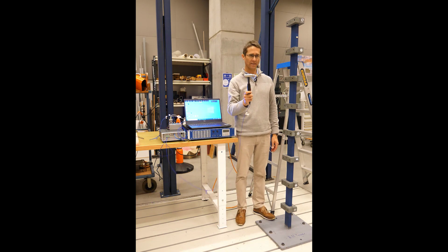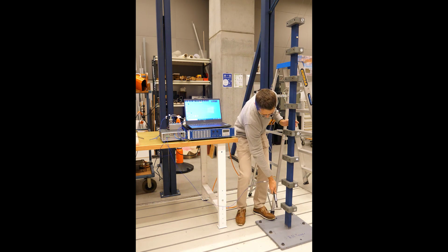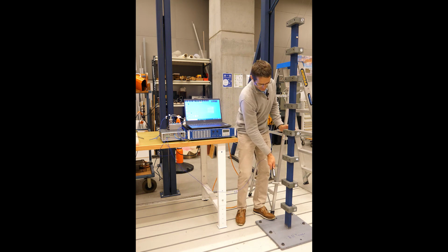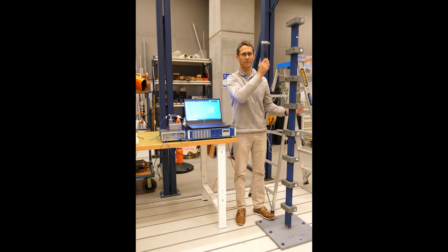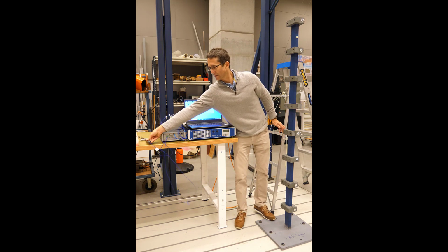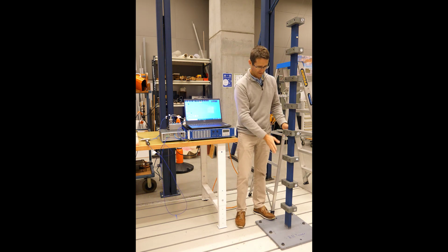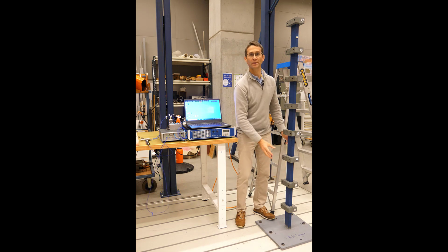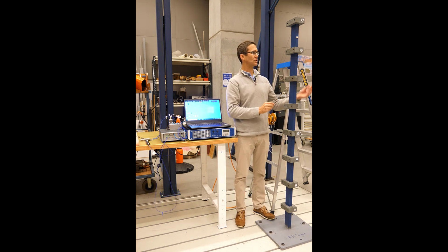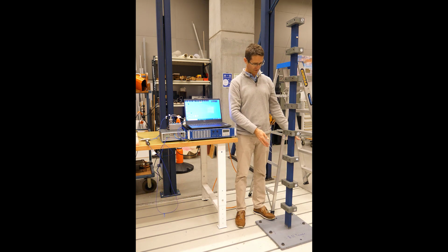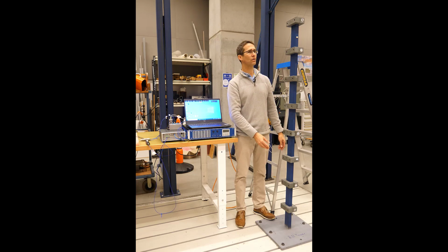modally tuned impact hammer to impulsively excite the structure at each of these various degrees of freedom in turn, and I will capture approximately 3 to 5 averages for each of these different towers and build an FRF set taking into account the response at each of these locations for excitations at the various degrees of freedom along the tower.